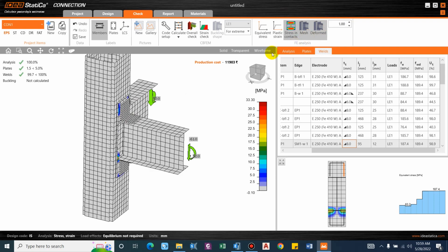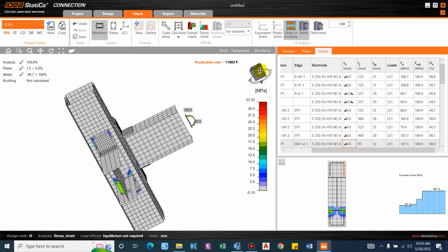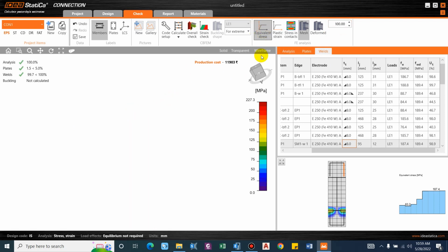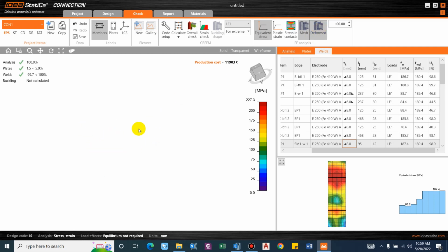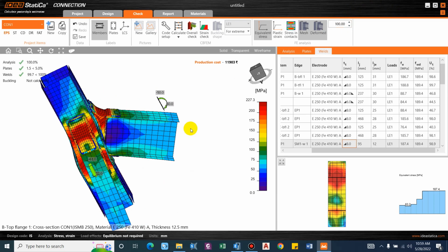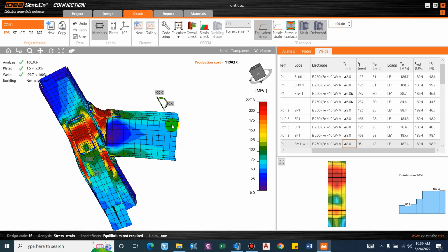You can also check the deformed shape and check whether it is according to our load provision or not. So simply go to this and check for the deformed shape now. I have basically increased the scale factor. So under the influence of the load of 50 kilonewton, you can see here.